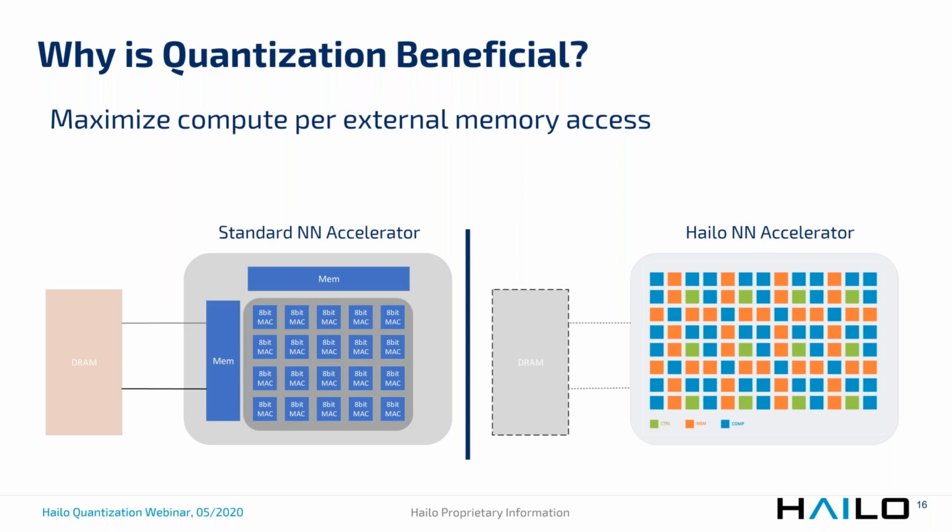A lot of modern chips are designed specifically to be neural network accelerators. We have to remember that while we focus on power consumption, we still need plenty of compute in order to implement neural networks with good performance. So neural network accelerators take advantage of the small size of 8 bits in order to have a lot more of them to create a large compute density. And they use a matrix-like structure to take advantage of the fact that we can reuse weights in several computations. So most standard neural network accelerators will have this main compute element that's like a matrix.